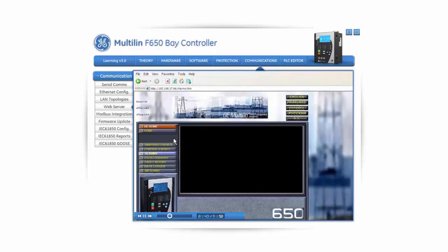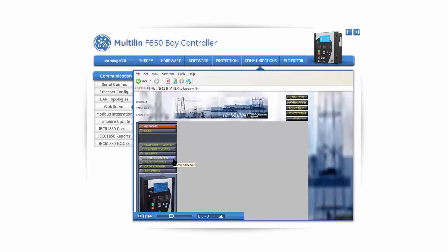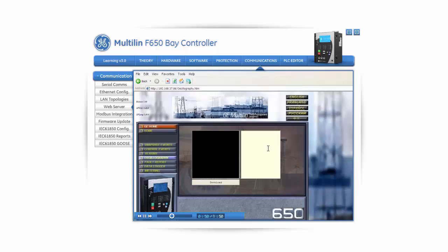The Alarms screen provides access to alarms configured in the relay. As was the case for the snapshot events and control events, this screen only allows viewing the alarms, but not acknowledging them. The oscillography screen allows the user to obtain from the relay available oscillography records in that moment.